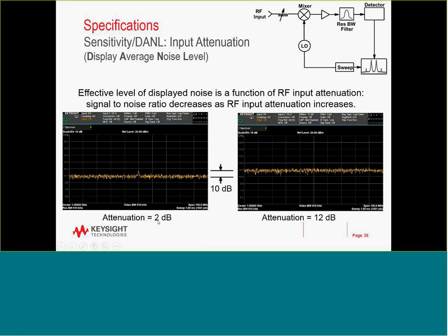In order to improve the matching, in this case, I lowered the attenuator but kept 2 dB in order to get a match. I could still go down to 0 dB, but that's not very good, and it adds some uncertainty to my measurement.